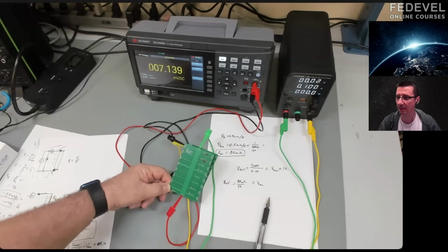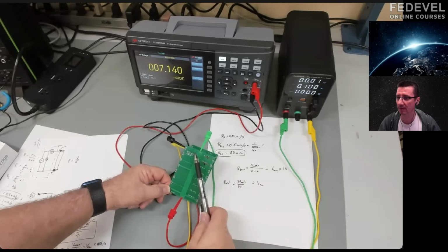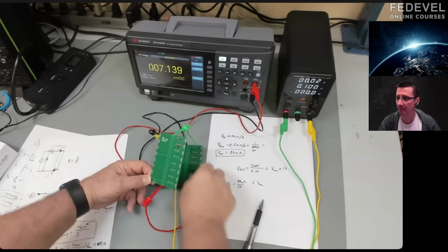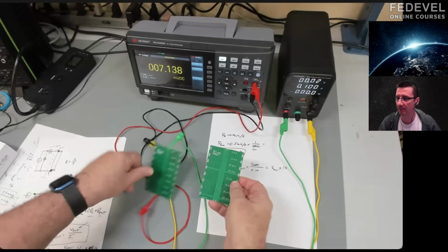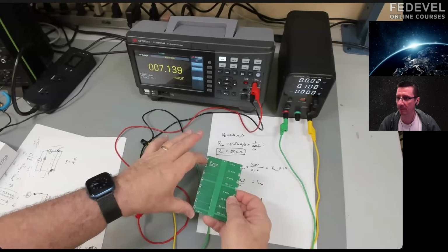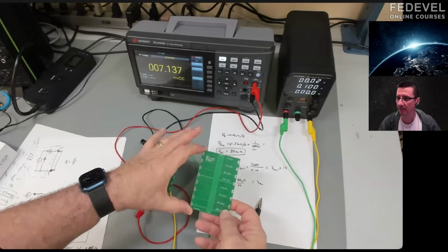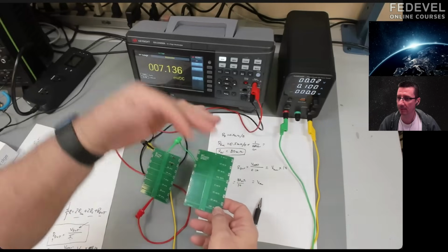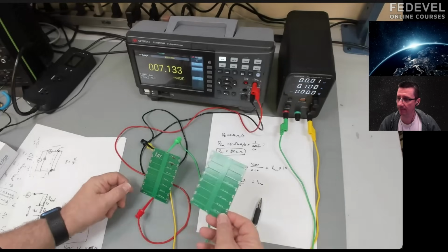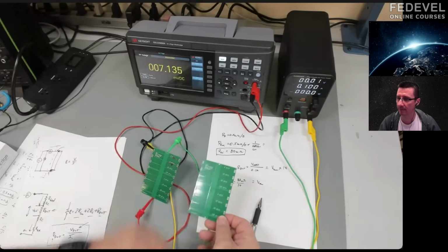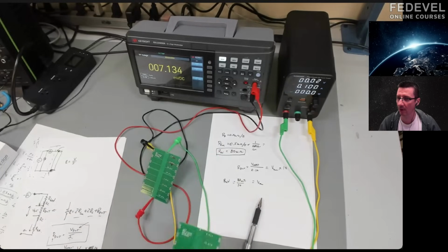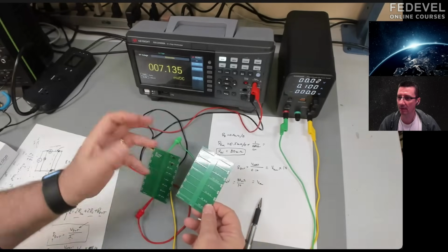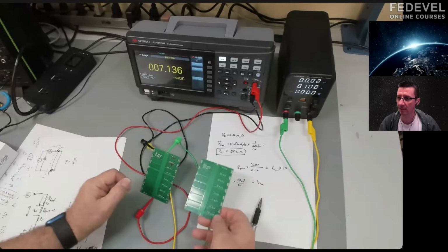It could also be, so this is a 6 mil wide trace. It could also be an etch back. It could be that in this board that had the low resistance, it wasn't really 6 mils. It might have been overplated plus a little wider because you get plating on the edge of the trace there. So this could have been overplated. This could have been etched back a little bit more. Hard to know unless we do a cross section or we do a measurement of the dimensions.